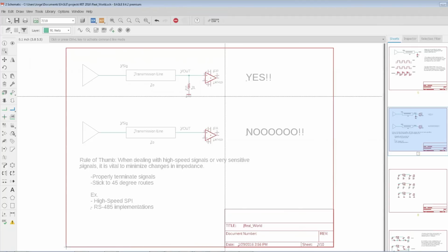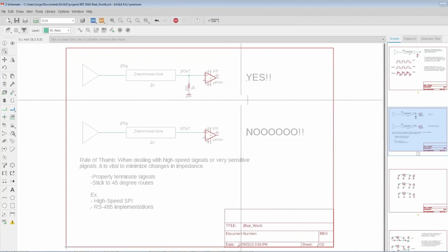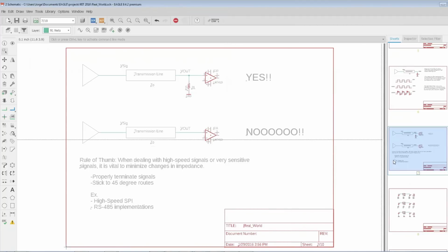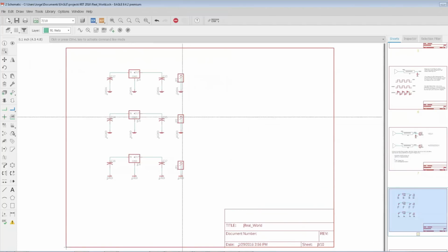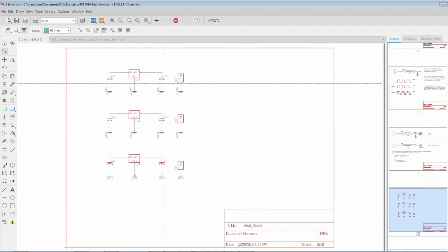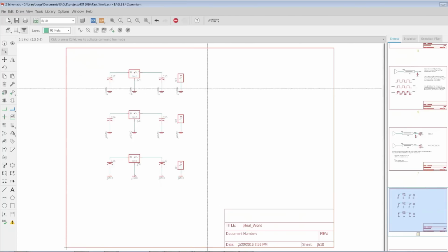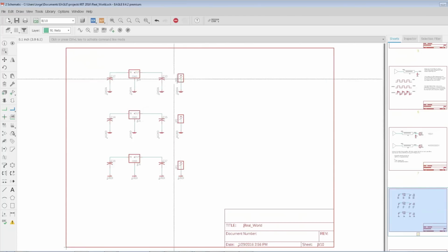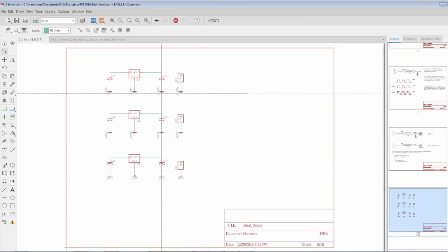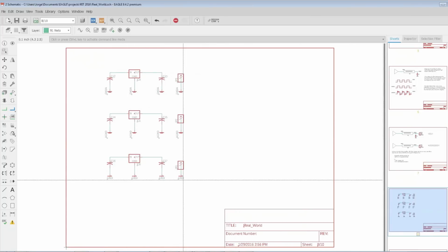Since we're talking about ground, let's go ahead and talk about this slide: the idea of ground and why just thinking in terms of a current sink is a problem, of just one big plane where putting everything through there means everything's going to be okay. If you look, these three circuits look identical, because they're all going to ground. But depending on how they're routed, you may run into issues.